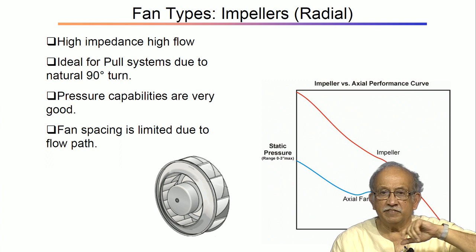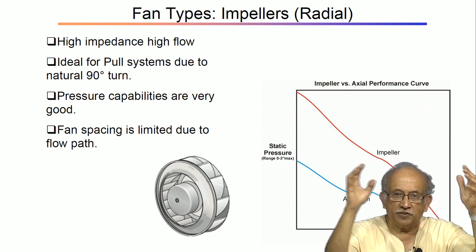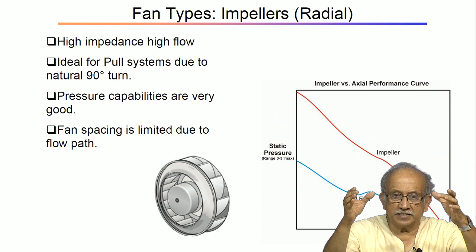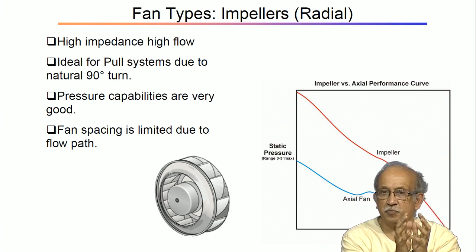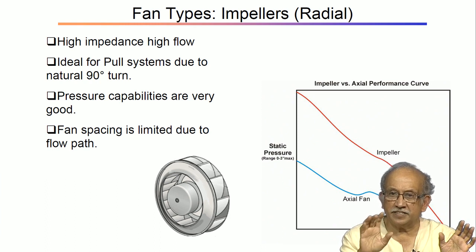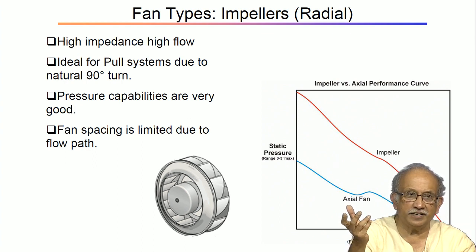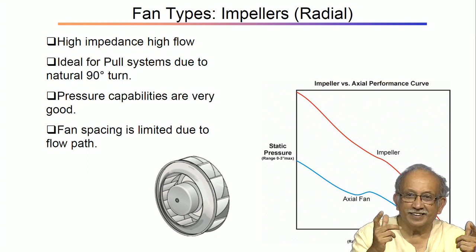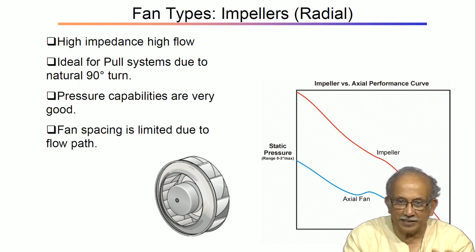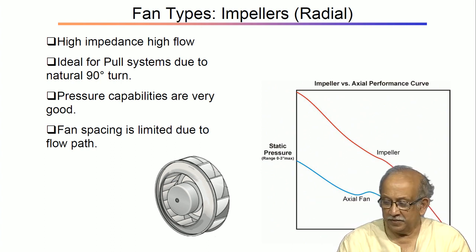You must have seen all those whirly bird ventilators on several roofs. The advantage of the whirly bird is that naturally something is rotating, and air starts exhausting. Both versions exist. One is helped by a small built-in motor, and some are motorless. As the air from outside comes, it acts like a natural windmill. Yes, I too had the doubt. A windmill impedes the airflow, but at the bottom you already have warm air rising. That is how a whirly bird works.